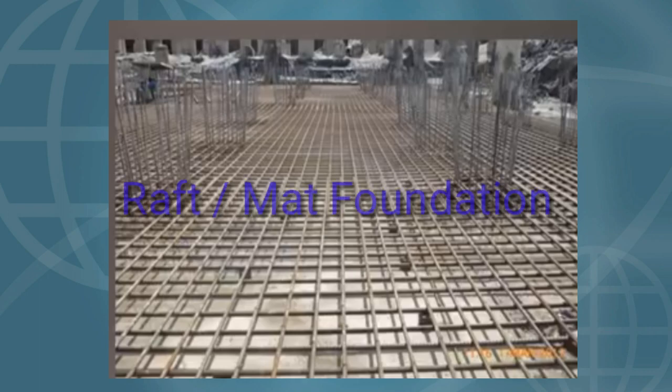Okay, next type of footing is raft foundation. This type of foundation is known as mat foundation. This foundation covers the entire area under the structure. This foundation has only a reinforced concrete slab covering the whole area, or slab and beam together. Okay, the raft foundation is adopted for a heavy structure.